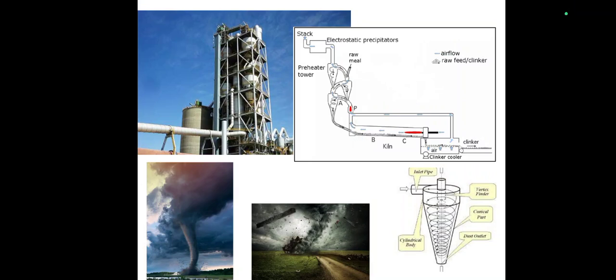So the main difference here, when compared to the wet mix, is that in the dry mix, mixing will be very difficult. So for that, the process they follow is that some hot air is extracted from the clinker and allowed to pass vertically towards the top in a circular fashion like a cyclone. You might have seen cyclones and hurricanes like that in foreign countries. It will be like a rounded circulation of wind. Like that we are artificially making it in this preheater chamber.